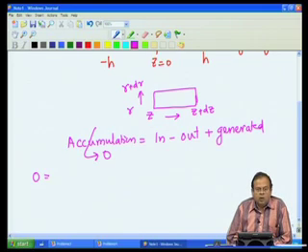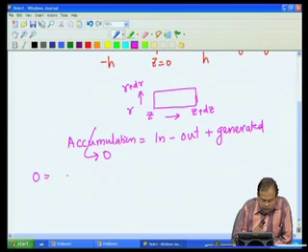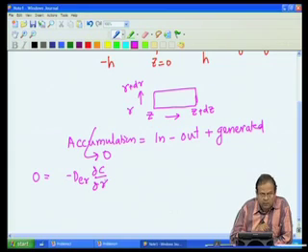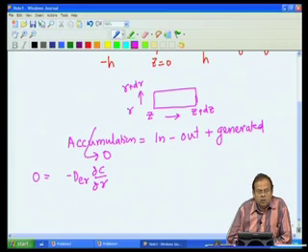Okay. Now, let us try to find out what is coming in. Coming in is both from the radial direction and also from the axial direction. So, let us talk about the radial direction. If my flux is minus D_r dou C by dou r, I am writing a small subscript r to say that diffusivity in the radial direction could be different from diffusivity in the axial direction, but that is a detail.